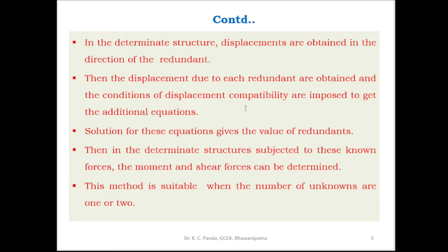Solution for these equations gives the value of redundants. Then in the determinate structure subjected to these known forces, the moment and shear force can be determined. This method is suitable when the number of unknowns is 1 or 2.